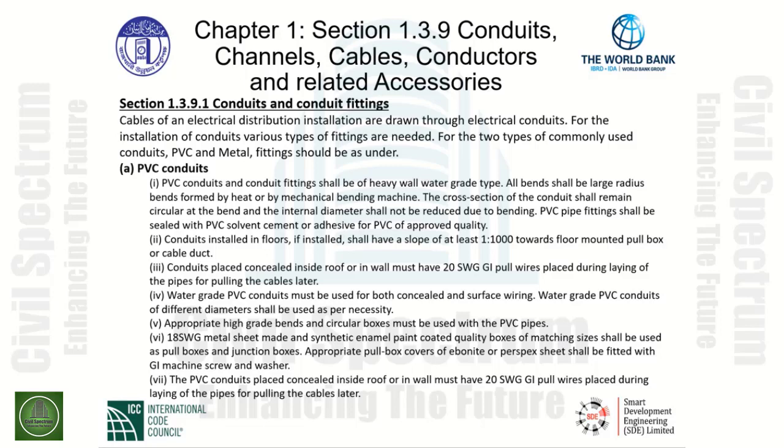Item number 1. PVC conduits and conduit fittings shall be of heavy wall, water grade type. All bends shall be large radius bends formed by heat or mechanical bending machine. The cross-section of the conduit shall remain circular at the bend, and the internal diameter shall not be reduced due to bending. PVC pipe fittings shall be sealed with PVC solvent cement or adhesive for PVC of approved quality.